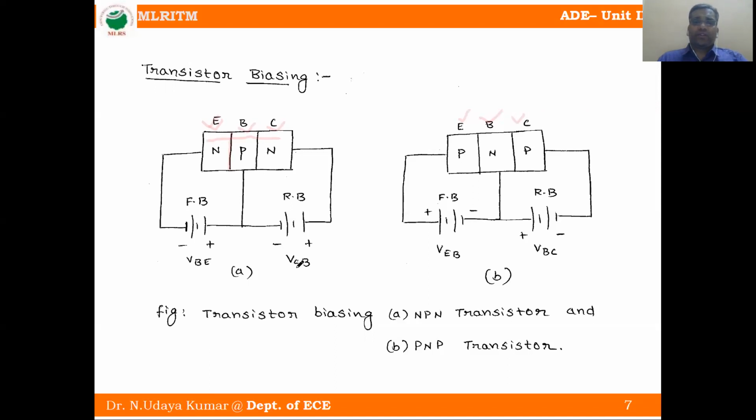Okay, here also there is reverse bias. So this one is the emitter, this one is the base. The emitter base junction is always forward bias and the collector base junction is reverse bias. Okay, we can change these biases and we will see different characteristics.